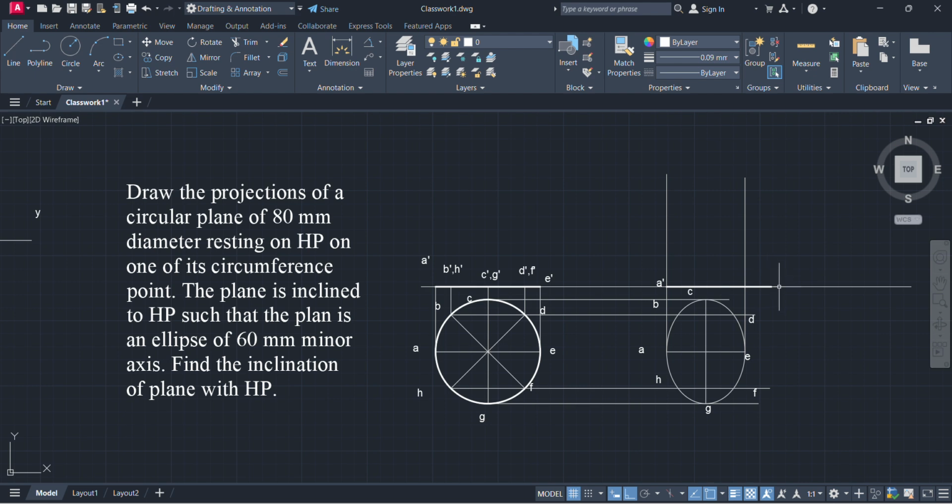Now there are multiple ways to go around it. What I am doing, I am drawing a circle with A dash as the center and the line length itself as the radius. So I know the entire length is 80 mm exactly. And then I can rotate the line with A dash as the center. So we will rotate this line so that it meets the intersection, and then I can delete the circle, and this will be my point E dash.